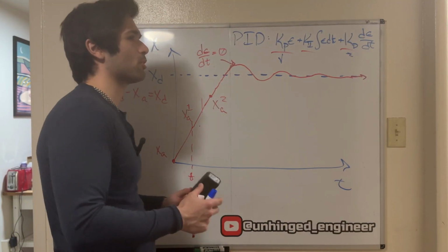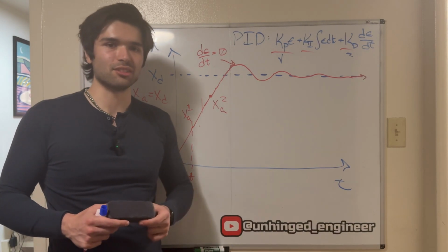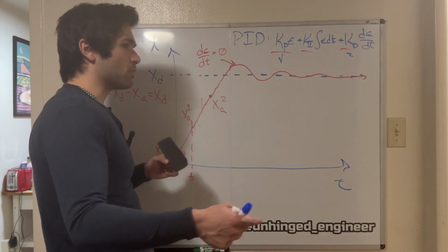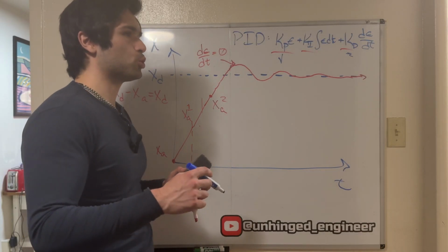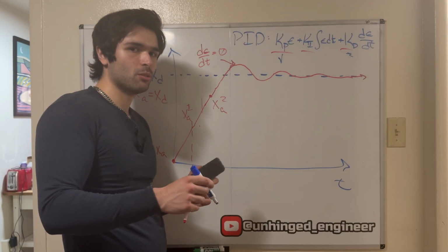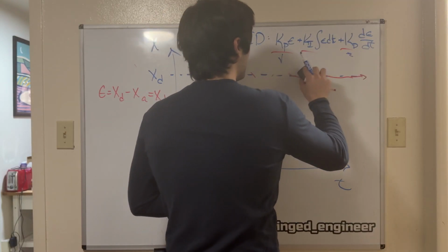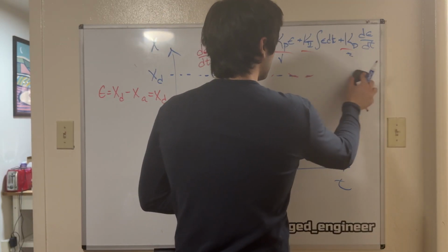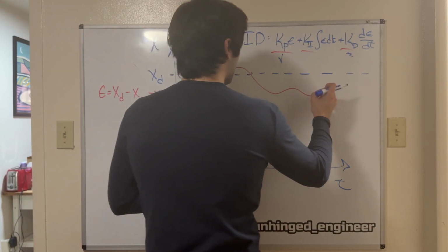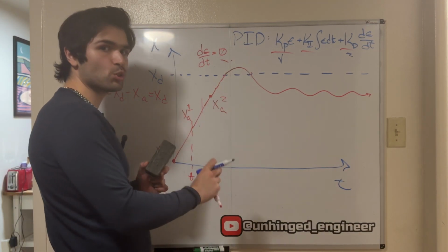But sometimes, let's just say for argument's sake, we mounted a motor wrong on our drone, or a resistor in the circuit that leads to the motor is busted and it's not getting as much voltage as we anticipate. Something weird is going on that makes it so that the control we're putting into the system doesn't actually match what's manifesting in the real world. What might happen is, with just a purely PD controller, you might actually converge to the wrong set point. So again, the magnitude of our oscillations are going down, and we're trying to drive our error to 0.